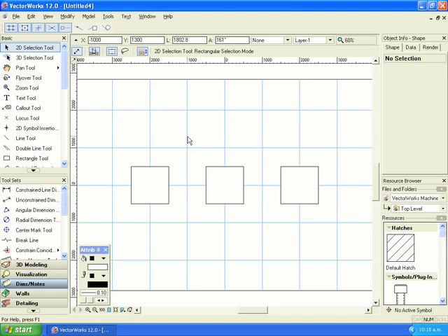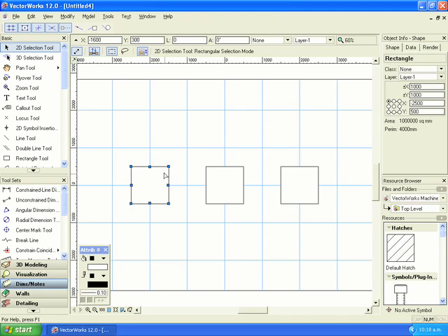This is our extrude file. The first rule of extrusion is that extrusions always come out of the screen at you, so they are view dependent. In the first example, we're in a plane view, so when we extrude it, this object is going to go up, and so it's going to come towards our eye.